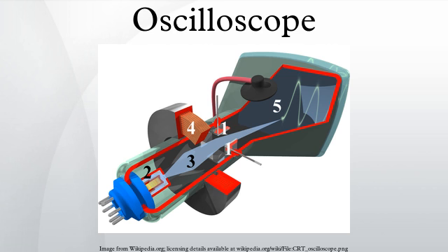For a period of time, called hold-off, the sweep circuit resets completely and ignores triggers. Once hold-off expires, the next trigger starts a sweep. The trigger event is usually the input waveform reaching some user-specified threshold voltage in the specified direction. In some cases, variable hold-off time can be really useful to make the sweep ignore interfering triggers that occur before the events one wants to observe.